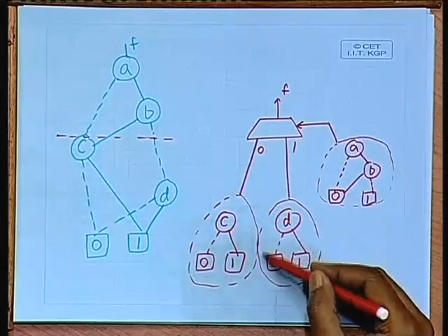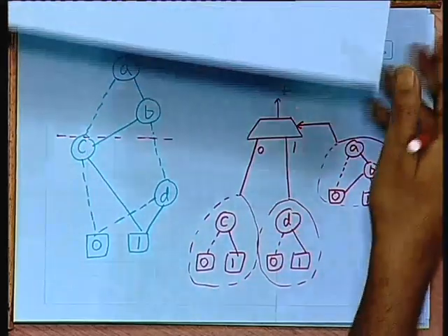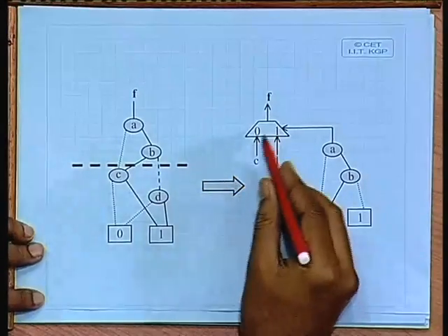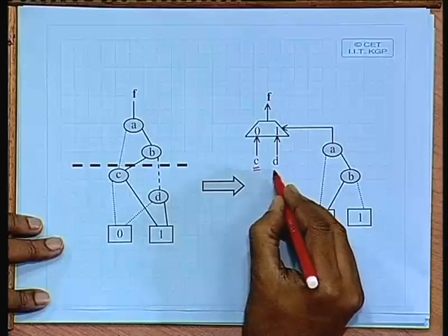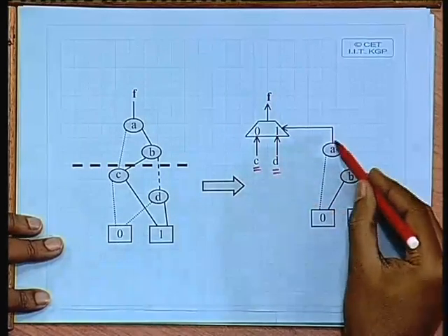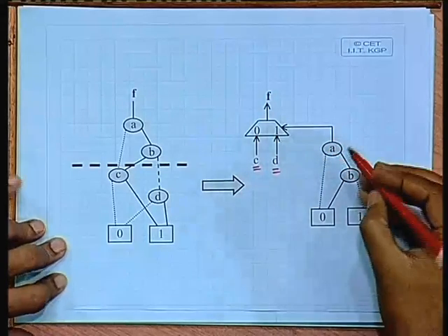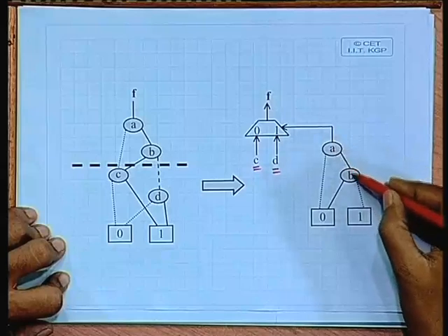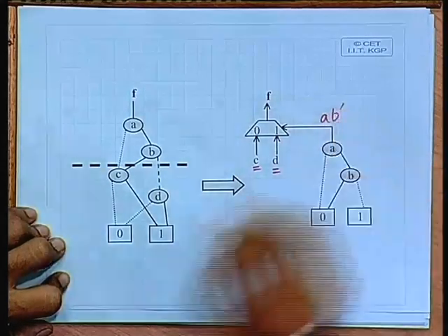So, this is the requirement of your function, and this one you see that this is simply C, this is simply D, and this, well, I am showing this diagram now. This is drawn in that compact form. The left input is simply C, right input is simply D, but what is this function? You can again follow that same rule, you trace all paths of the true minterm A B bar. So, this actually is the function A B bar.